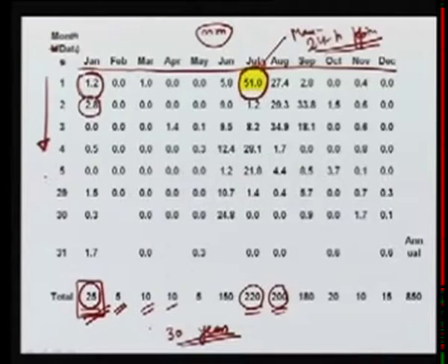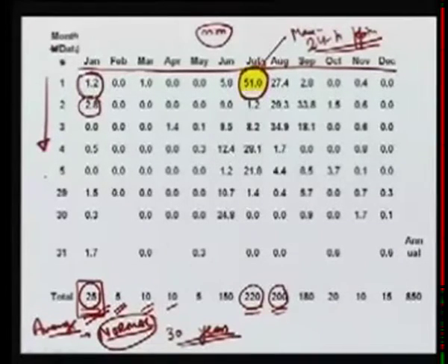So we can find out an average. The 30-year average is typically known as the normal precipitation. So we can say that in the month of January, normally the precipitation will be, let's say, 27. At least a 30-year record is generally used, but sometimes smaller periods may also be used.